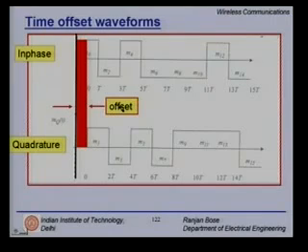So this offset will ensure it's in between a bit, that phase shifts can never be 180 degrees. They can be at most 90-degree phase shifts. Because even though QPSK is dealing with 2 bits at a time, at any time instant, 2 bits cannot change at the same time, because I am only feeding one new bit per bit interval.